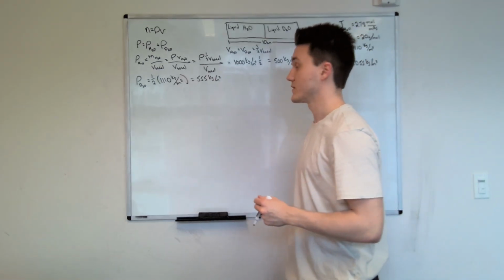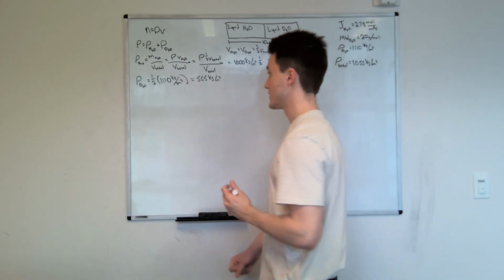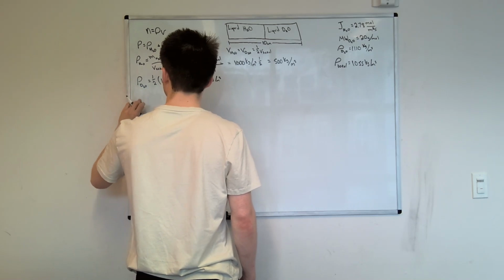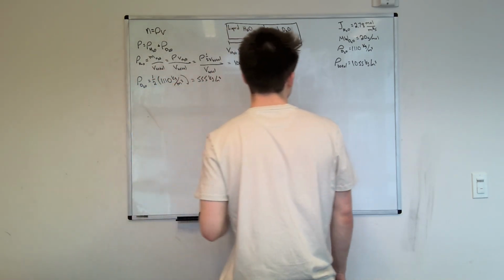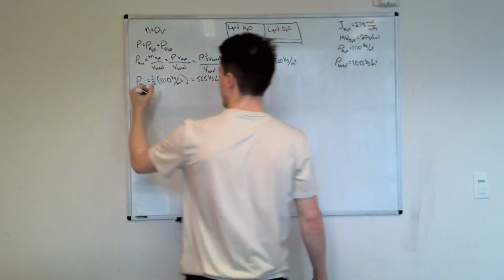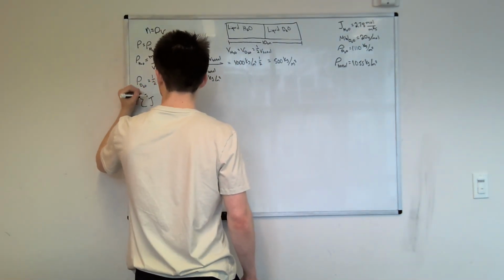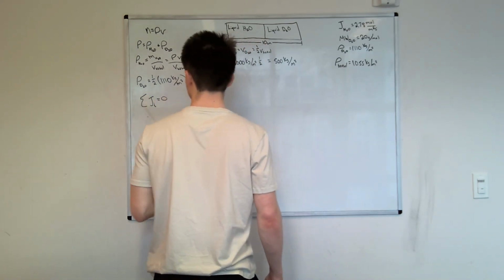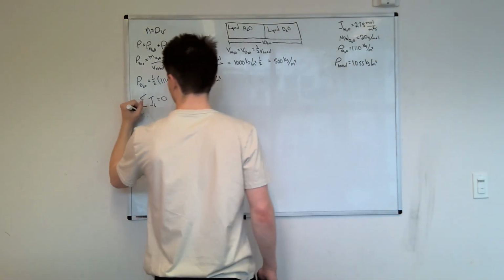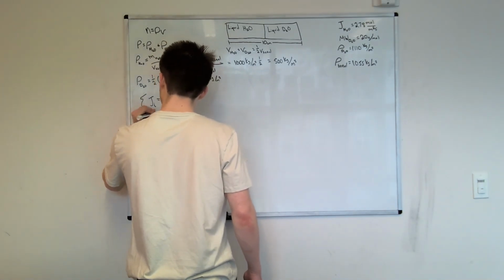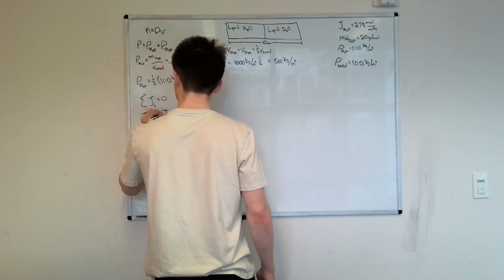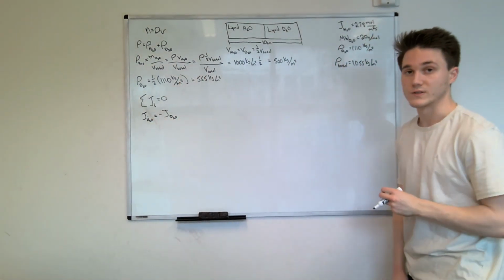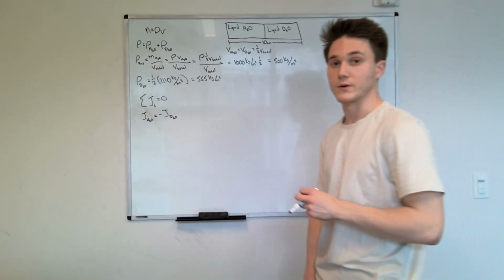And next, we want to solve for the mass average velocity. And we know that the system is closed, making the sum of the molar diffusive fluxes equal to 0, making the molar diffusive flux of D2O equal to negative 2.78 moles per meter squared per second.